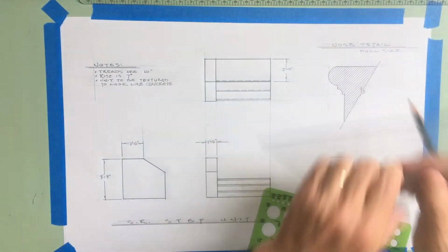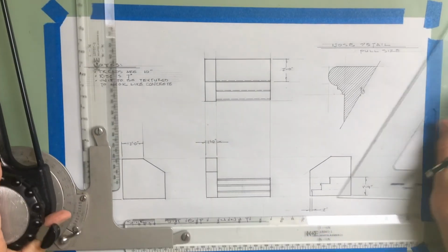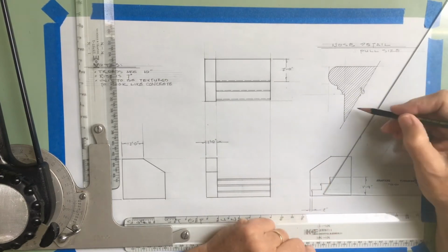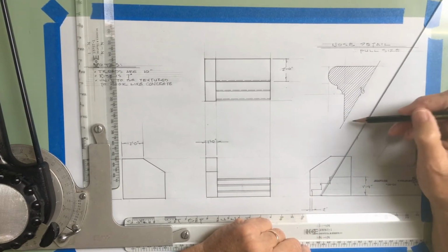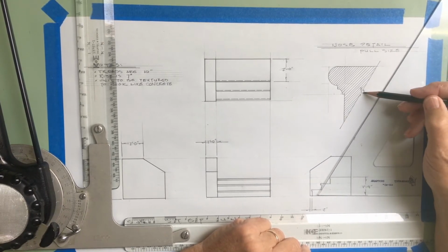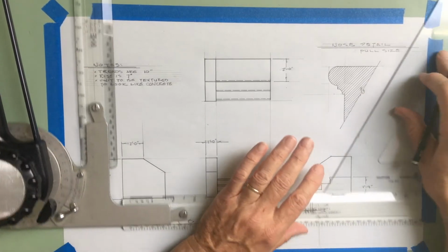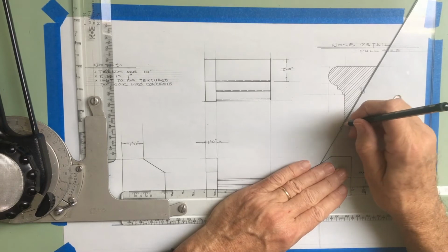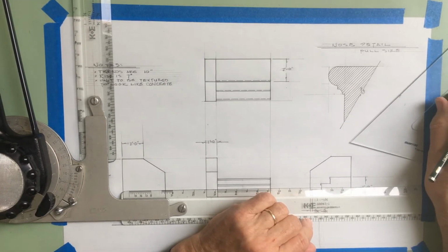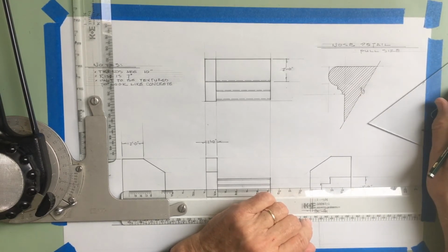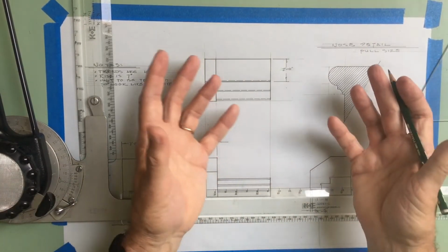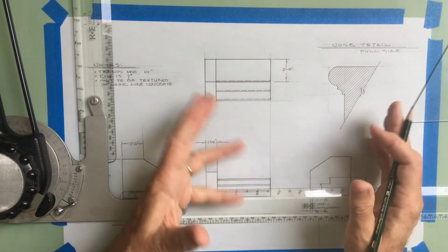The other thing I've done here is I've finished this. Instead of having to draw a full-size section view of the entire thing, I can use this specialized line called a break line. It goes past the perimeter of the object on both ends, and somewhere in the middle it has a little squiggle. And in this case, I just drew it with the 30-60 triangle, and that indicates that I've broken away part of this that I don't need, that's irrelevant to the meaning of this drawing, and just included the parts that are relevant. That's called a break line. It's basically for breaking a piece, removing some of it, and just keeping the part that's descriptive.